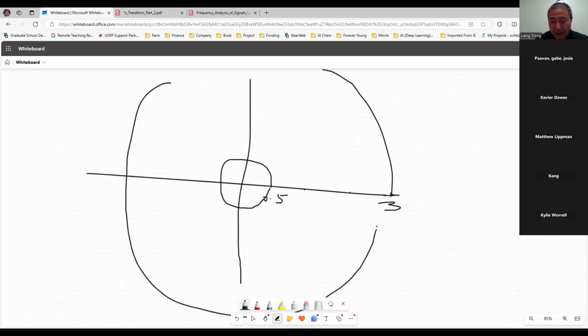It's large. So it's like this, right? And then these two poles cannot be in the region of convergence. So the region of convergence should be strictly greater than or less than, so exclude these 2 points. For example, the exterior of this circle of 3 can be a region of convergence, right? It is strictly larger than these, so it excludes these 2 points.